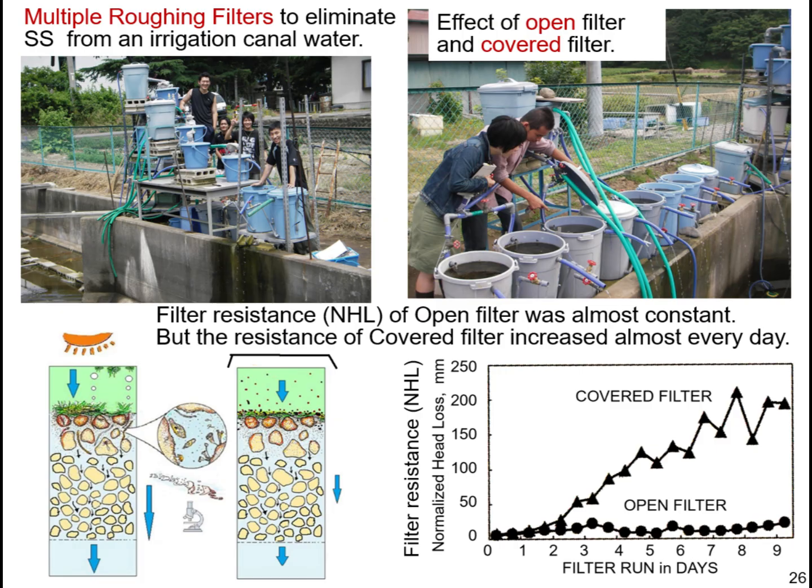I examined multiple roughing filters to eliminate suspended solids from irrigation canal water. I also examined the effect of open filter and covered filter. Filter resistance of the open filter was almost constant. But the resistance of the covered filter increased almost every day.